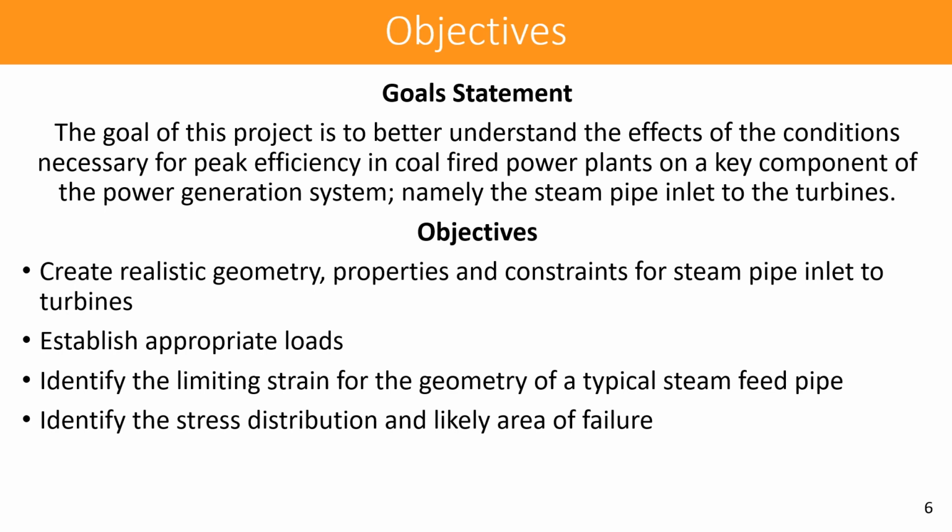Then, to establish the appropriate loads. Using that wholly constrained geometry, run a simulation to identify the limiting strain for the geometry of a typical steam pipe, and then identify the stress distribution and the likely area of failure.